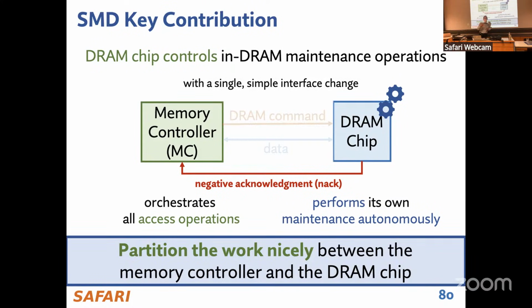So it's a very heavy-handed solution. You need a much more finer-grained solution so that you don't destroy performance. And we showed that, actually, if a RowHammer attack can induce a lot of alert backoffs, your performance becomes much worse, right? And at low RowHammer thresholds, you will get that alert backoff. So disabling the entire DRAM chip so that it can do RowHammer maintenance is not a good idea. And this is demonstrated many times.